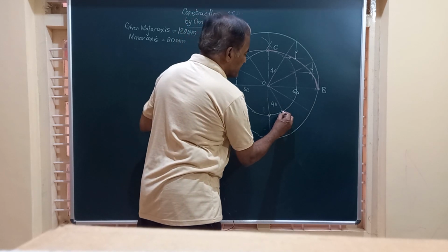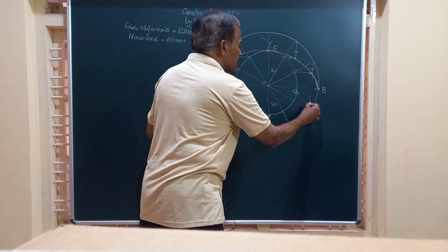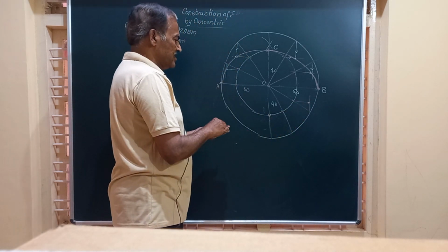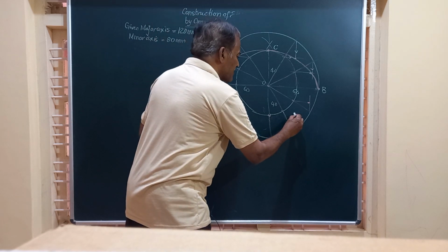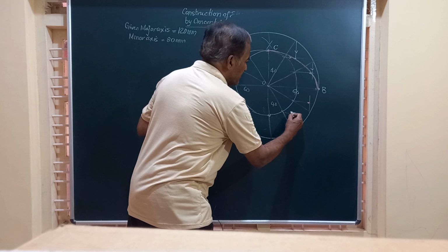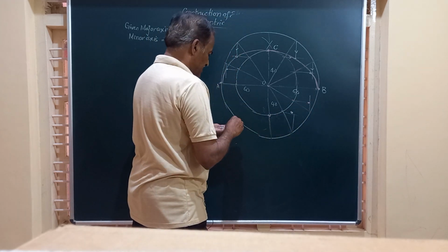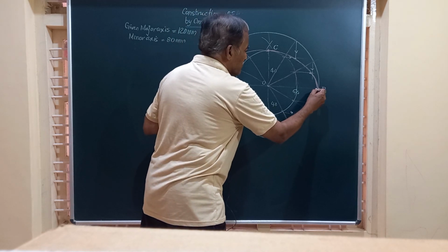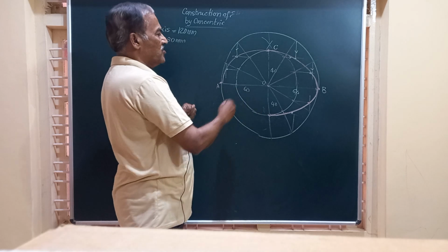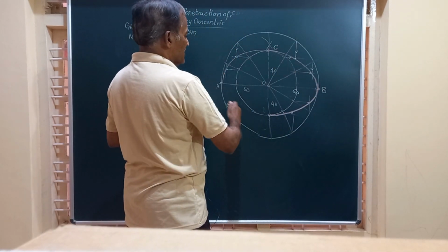Now here friends, you can see, follow the same procedure, vertical line from this, horizontal line from here, they meet at this point. Similarly, vertical line from this major axis, horizontal line from here, they meet at this point. So you got 1, 2, 3, 4 points, join them by a smooth continuous curve, friends. So we have got ellipse, first quarter, second quarter, third quarter.